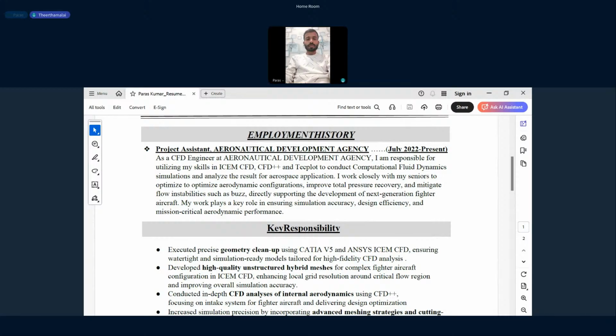So when it is over expanded, the exit pressure is lower than the outside pressure. To satisfy that, the shock will come. There are some criteria also: it should be less than 0.4 of that exit pressure. Then only will the shock form. Otherwise it will go and the shock will not form.